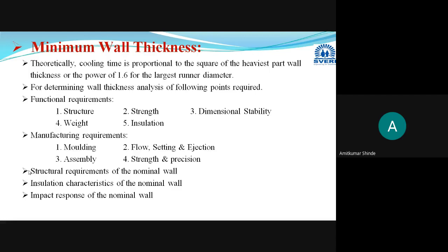At that time also I will decide it, but just consider here what is the purpose of giving that extra. These will act as accessories or extra support. Ribs and bosses will provide strength to that particular part, so that it will sustain the stress created while it is under the loading condition.